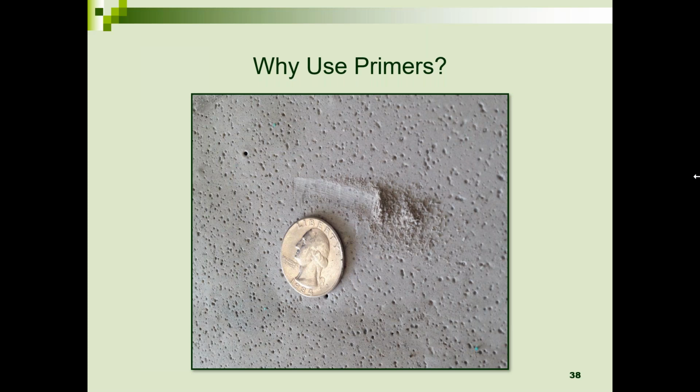So primer is very important. It should not be taken lightly because it dramatically affects the performance of the underlayment. Earlier we showed the ingredients in an underlayment, the recipe, all the various components. You start playing with the water, you dramatically change how those various components react with one another. So water is very important. Once you mix it in, make sure it's not absorbed by the substrate, as we've shown in the last few slides.